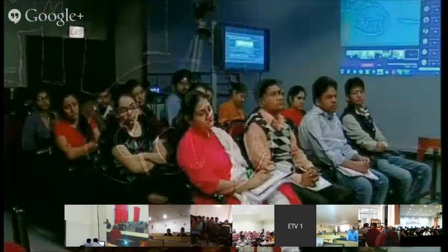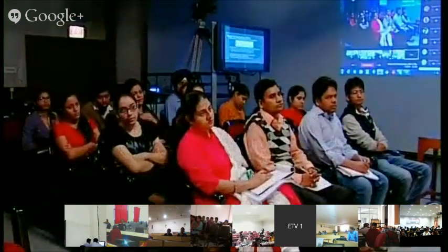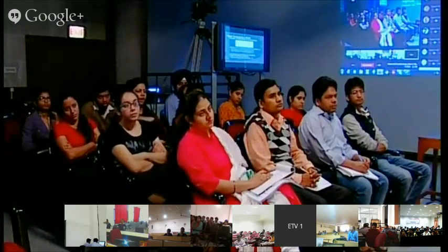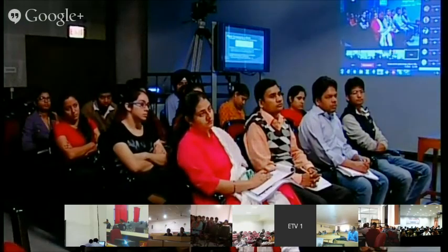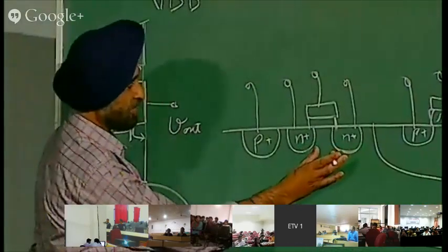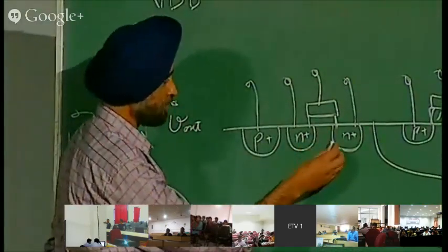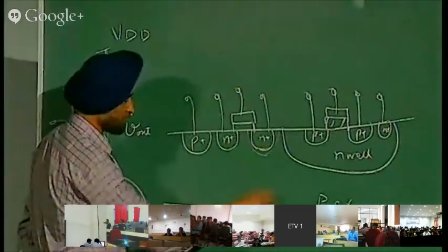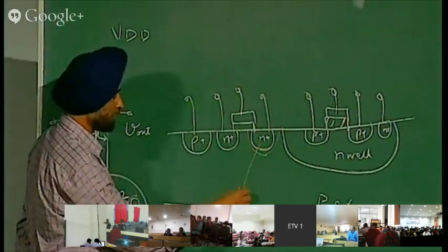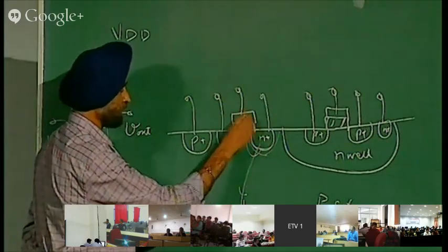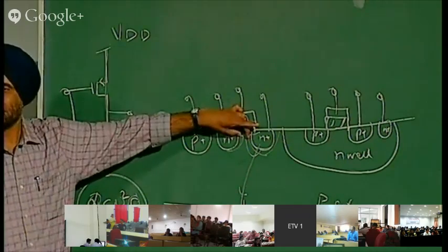Okay, so what about standby power? From here to here it is almost zero. But when you shrink the transistor, meaning you are reducing this side, there are leakage powers. There are around 5 types of leakages in a transistor, happening from source to body. This is the substrate; there will be some leakages from here also, from here, and from here. All these leakages constitute the standby power, because the channel length is decreasing.